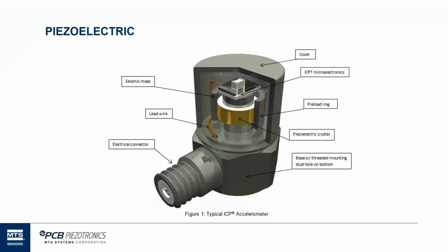And the preload ring is a material specially designed to apply very repeatable deformation when it's heated or treated in a certain way, and then when the heat is removed, it contracts to clamp all of that mechanical structure together. And it's a one-time set type thing. So if that temperature is applied again in the future, we don't get another loosening effect of that material. It stays tight, and that's unique to that material.